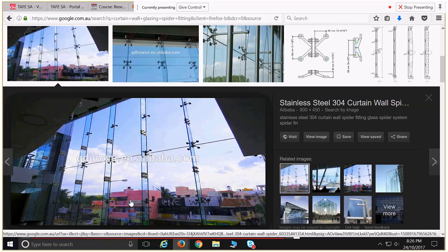So it provides strength for racking forces, for the wind pushing against it. And these fixings are what are known as spider fixings. So this detail relies upon holes being cut in the glass, so holes drilled. That'll be done in the factory, in specified locations. And then you have those spider fixings fixed to these glazed mullions, and they've got their little chrome end caps on them, etc. And then you have silicon joining between mullions and the glass.